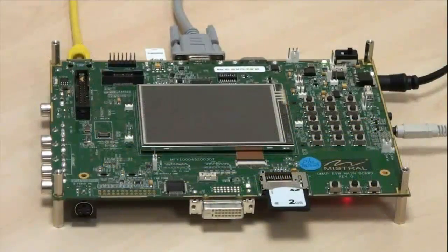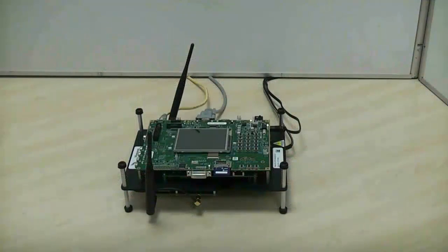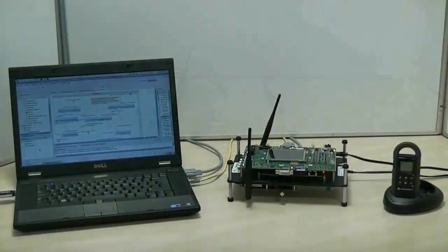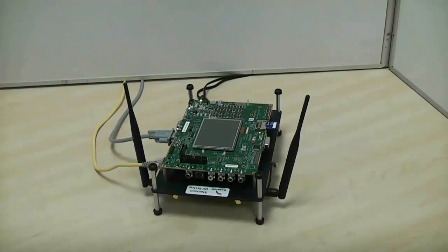The platform configuration includes a Mistral OMAP35X board providing baseband processing resources including general-purpose processor and digital signal processor, the DataSoft Monsoon RF transceiver providing FPGA resources and RF functionality, PrismTech's benchmark setting SCA 2.2.2 compliant operating environment that includes a core framework, radio services and devices, Object Request Broker, Corba services, Wind River's VxWorks real-time operating system, device drivers, and board support packages. Also included is a demonstration SCA waveform application, documentation, all available off the shelf with simple